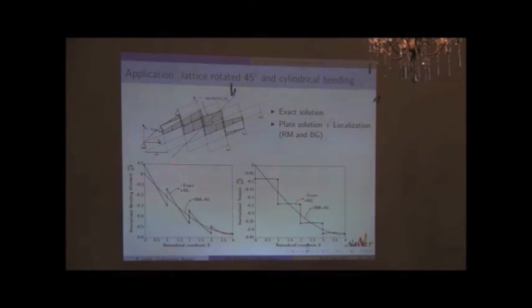And what you see is that if you use the Kirchhoff law approximation, you have the red curve for the estimate of the bending moment, the local bending moment inside the beams, and the same for the normalized torsion. So you have this sine shape distribution. Whereas the exact solution and the bending gradient fit very closely together, and you can see this jigsaw pattern, this stair pattern.